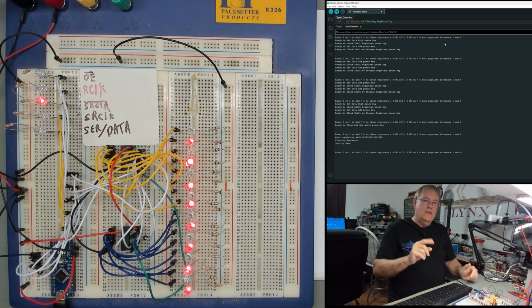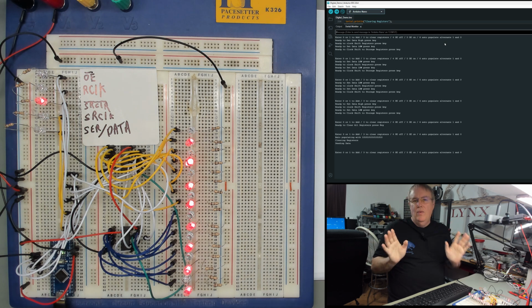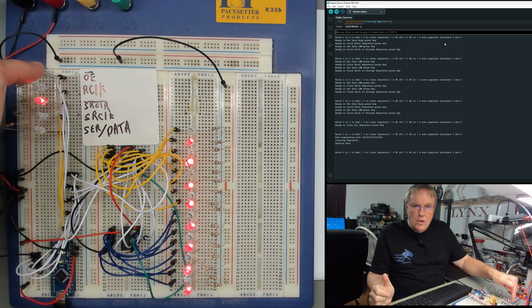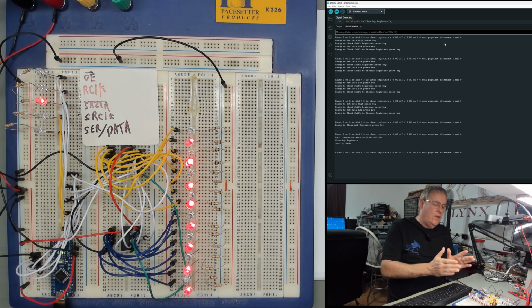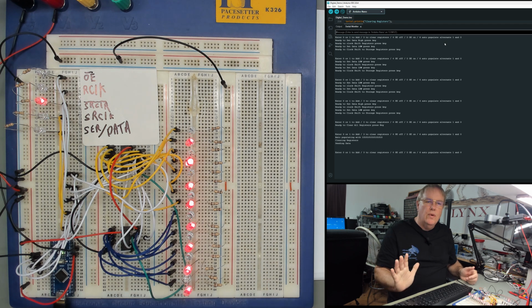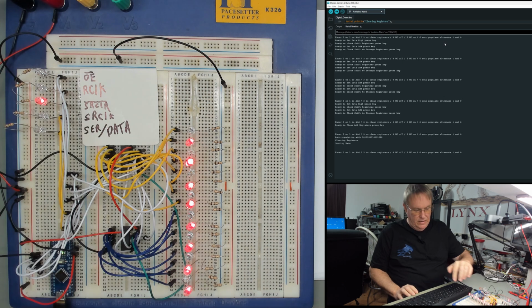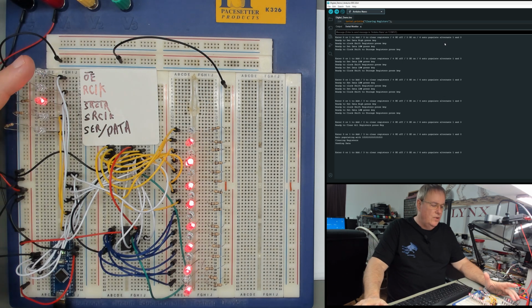What we can do is let's talk about the output enable. We haven't played with that yet, but remember the output enable is when you pull it low, it enables the output. Okay, it's been low pretty much all the time. But if you wanted to shut that off, maybe you want those lines to be turned off while you're making a change, or maybe you want to turn them off because you want to let other chips hooked to the bus of these connections control those lines, and you don't want to pull them low or pull them high. You want to say tri-state, as we talked about, and let other items on the bus on these data lines control these lines. We would want to use the OE to do that.